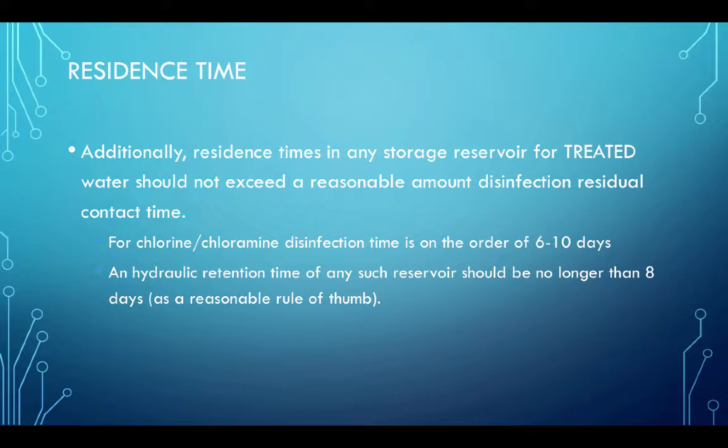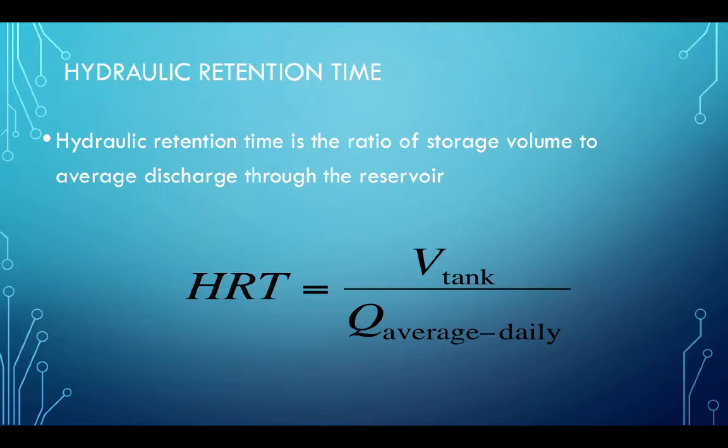For different types of disinfection processes, that disinfection time might be quite short. The one that comes to mind is hydrogen peroxide and ultraviolet visible light disinfection. They don't leave any residual, so you couldn't store that water very long and still declare it treated.